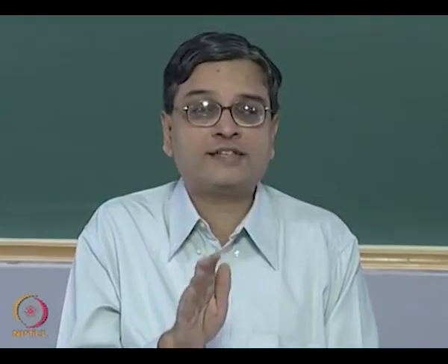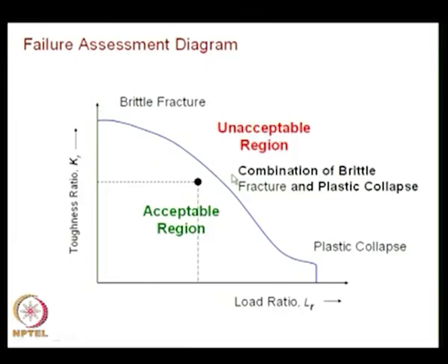People have shown examples where it satisfies LEFM independently, it satisfies plastic collapse independently, but still the structure is not safe because the point was lying outside the FAD curve. So, such examples people have demonstrated, and you have to take knowledge from that.